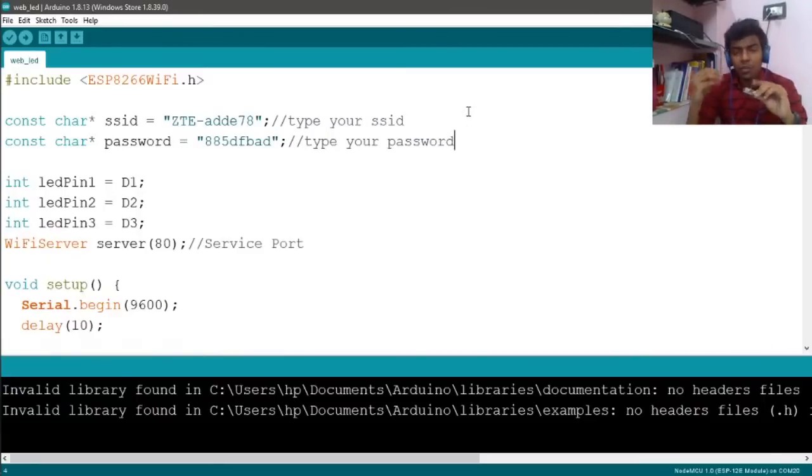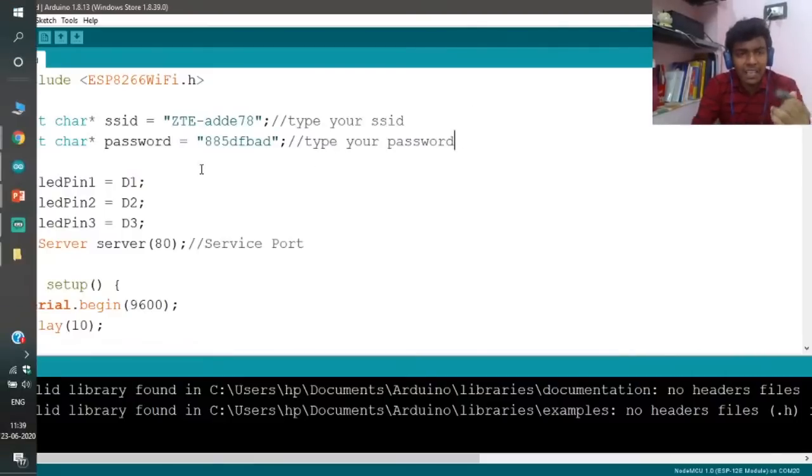If you are going to use any IoT based application, we need to connect with the internet, right? If I need to access YouTube on my mobile phone, I'll turn on the Wi-Fi or turn on the data. If I take Wi-Fi, I'll choose the right username and enter the password to connect my mobile with the internet. Same as this, for the IoT device I have to enter the username and password of my local Wi-Fi. So I have set the constant characters SSID and password.